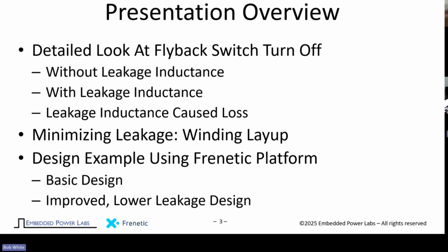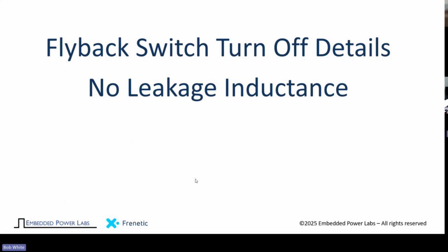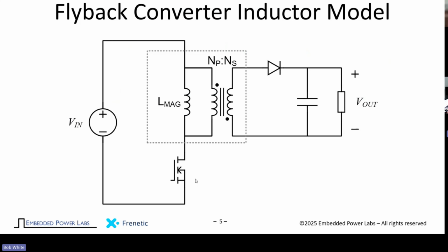But really, the goal is to minimize the leakage in the first place. And that really comes down to the windings. Then I'm going to use the Frenetic platform to show how you can explore different windings and different designs to get an improved design with lower leakage.